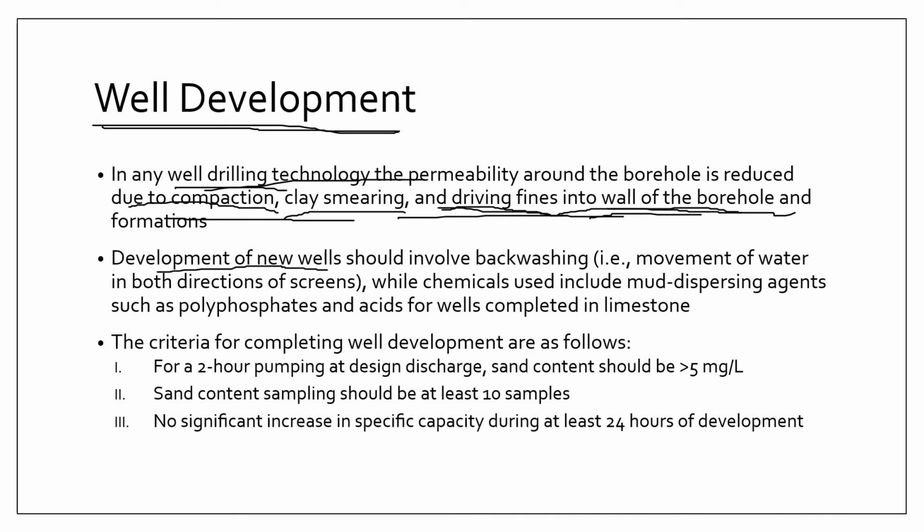For newly constructed wells, development should always include backwashing, or the movement of water in both directions of the screens. It means pumping in water and pumping out water to ensure that the water is actually moving in and out of your screen.